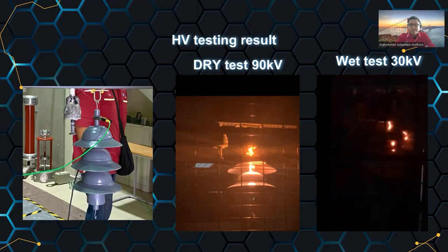Next we run the wet test, where we spray the insulator with salt water, assuming this prototype is in rainy weather.